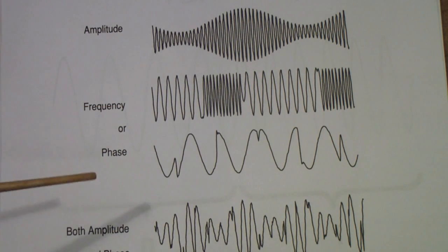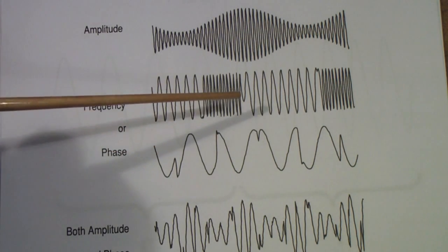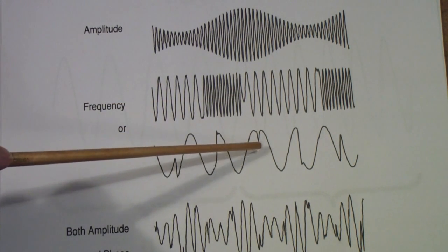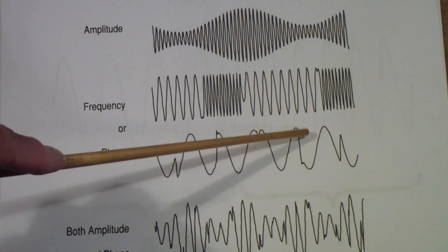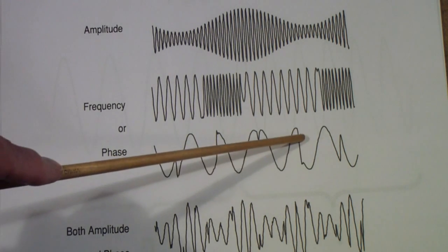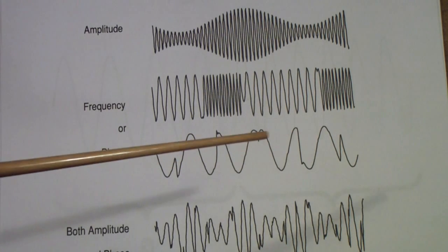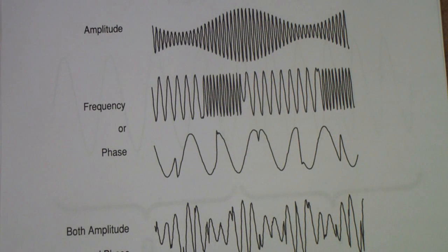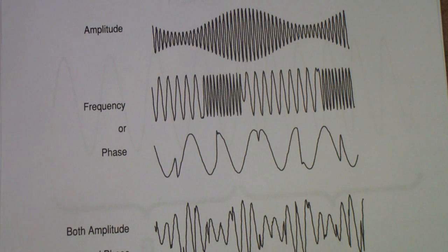And the reason for that is, particularly when you're doing frequency or phase modulation, the discontinuities in the waveform, in other words, the places where there is a steep, essentially infinite slope between one part of the waveform and the next, are the ones that cause the most trouble in digital communication channels. As a result, there have been many attempts over the years to find ways around that problem. One of the ways is through the coding methods that we talked about in concepts and in applications.